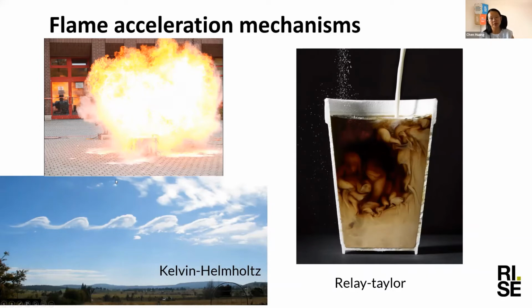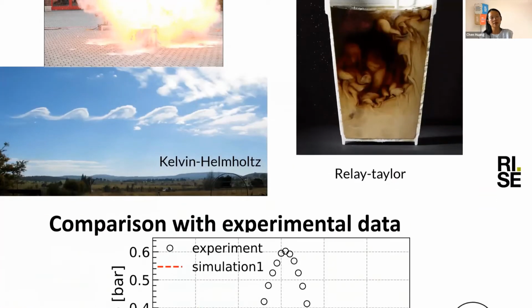many literatures say that hydrodynamic instabilities, Kelvin-Helmholtz or related, are the reasons for those instabilities and flame accelerations. And we include that by including some statistics from the gas flames, and increase the turbulent burning velocity with a factor, a power of square root of time, in the model. And here are some results